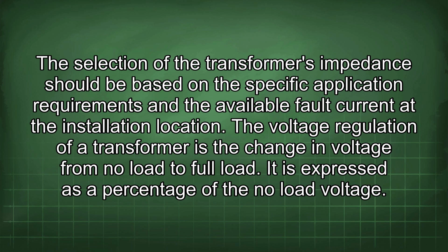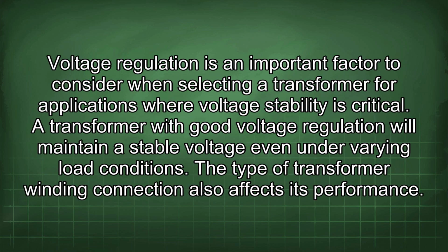The voltage regulation of a transformer is the change in voltage from no load to full load. It is expressed as a percentage of the no-load voltage. Voltage regulation is an important factor to consider when selecting a transformer for applications where voltage stability is critical.